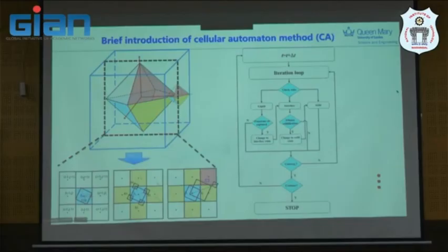Usually the neighbor cells are liquid cells, and the interface will catch the neighbor cell as interface 2. And meanwhile, there's a square appearing too. During the solidification, these squares will grow up and catch the neighbor cells. Finally, the interface cells lose the capture ability when they change to a solid cell.